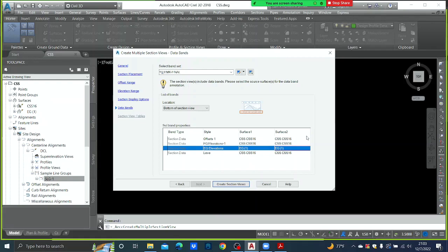they are giving the edges, and then maybe the edge of the lane, the edge of the hard shoulder, and the edge of the soft shoulder, like that. That is why we create a surface using the corridor. Otherwise the center line will suffice. Then this is level. There's no L here. So surface 1 minus surface 2, EG. That is going to give the level difference everywhere.